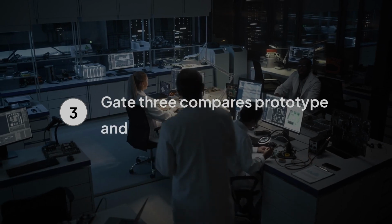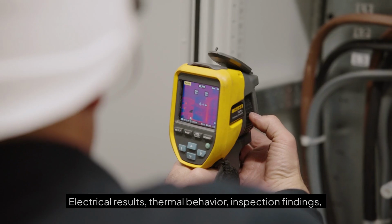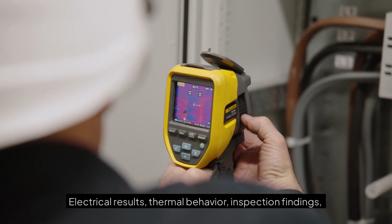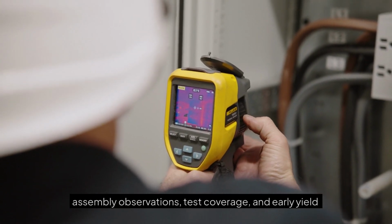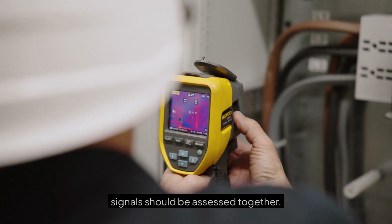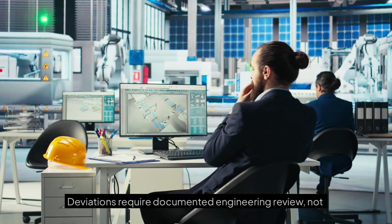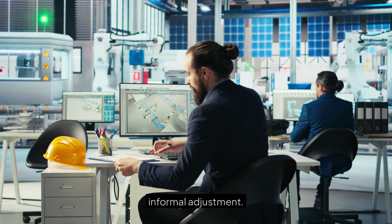Gate 3 compares prototype and pilot build measurements with design assumptions. Electrical results, thermal behavior, inspection findings, assembly observations, test coverage, and early yield signals should be assessed together. Deviations require documented engineering review, not informal adjustment.